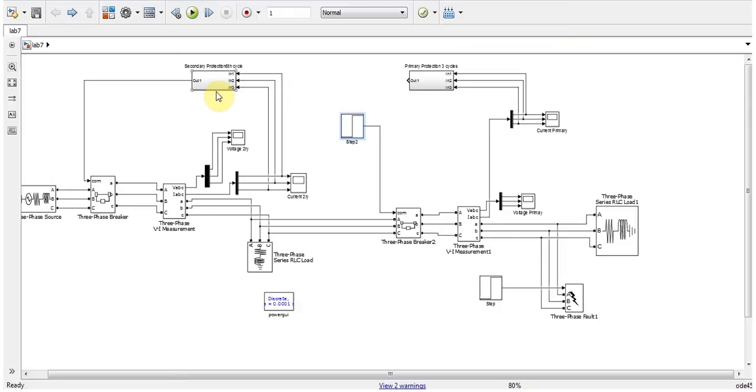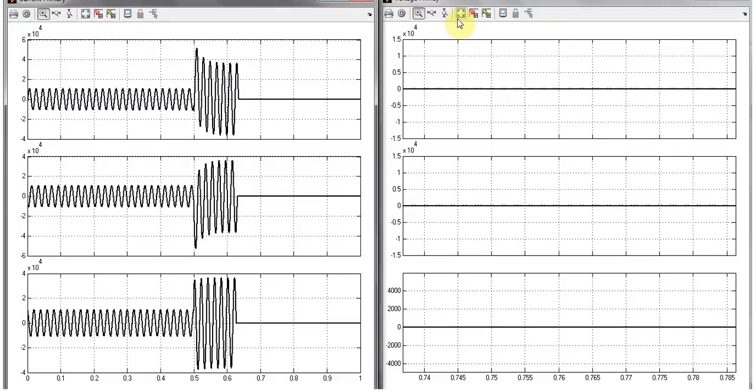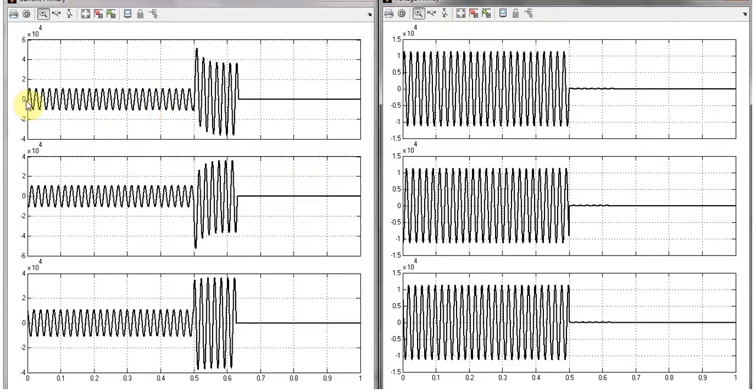Now it is the responsibility of the secondary protection to work after 6 cycles and isolate both this load and this load. Now let's run the simulation, and we hurry up to complete. Now as you can see in the current and voltage graph, first of all we're getting normal current, and then the current gets overshot, and then it is tripped off after 6 cycles, 1 2 3 4 5 6 and 7 cycle, because it has to get to the 0 value to trip off this relay.